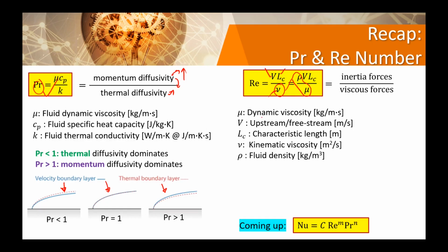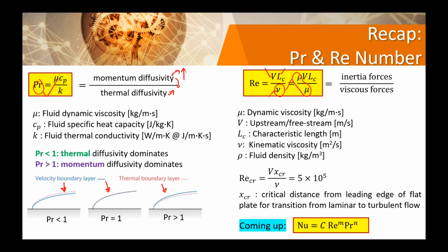All right. Why do we care about Prandtl, Reynolds number, on these dimensionless numbers? Because when we analyze convection heat transfer, a lot of the background works for obtaining the H, the convection heat transfer coefficient, is from correlations like the one below. Okay, you see the Nusselt number is the function of Reynolds number and Prandtl number. C is a constant, yeah, it's a number.